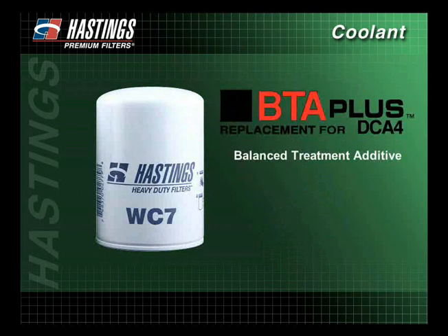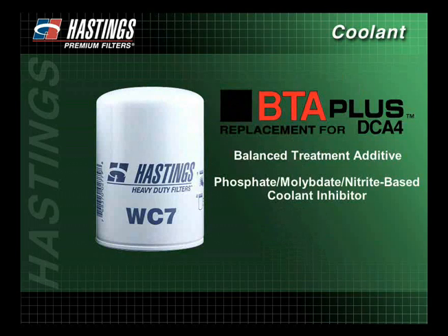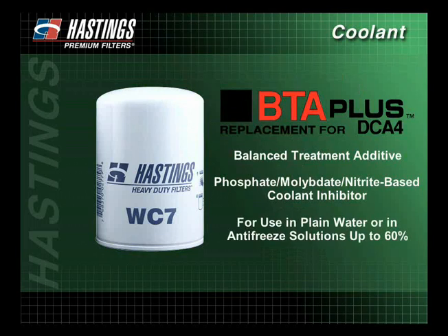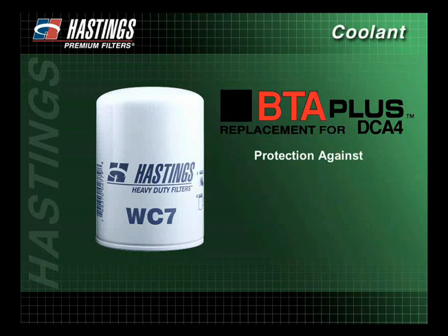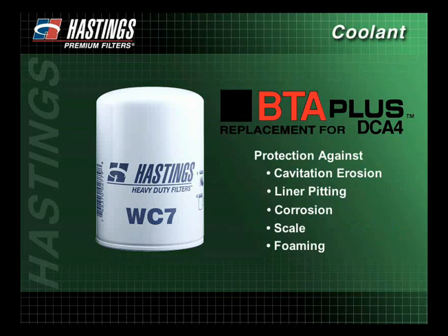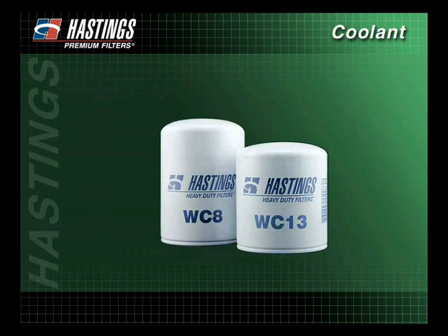BTA Plus, or Balanced Treatment Additive, is a phosphate molybdate nitrite-based coolant inhibitor designed for use in plain water or in antifreeze solutions up to 60%. BTA Plus provides excellent protection against cavitation erosion, liner pitting, corrosion, scale, and foaming. For those who prefer to add liquid SCAs to their cooling system, coolant filters without SCAs are also available.